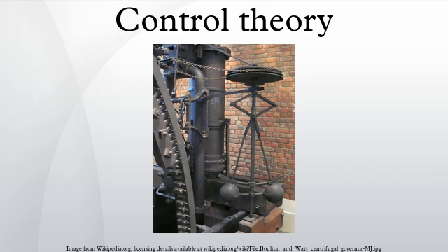The Sidewinder missile uses small control surfaces placed at the rear of the missile with spinning discs on their outer surfaces. These are known as rollerons. Airflow over the discs spins them to a high speed. If the missile starts to roll, the gyroscopic force of the discs drives the control surface into the airflow, cancelling the motion. Thus, the Sidewinder team replaced a potentially complex control system with a simple mechanical solution.